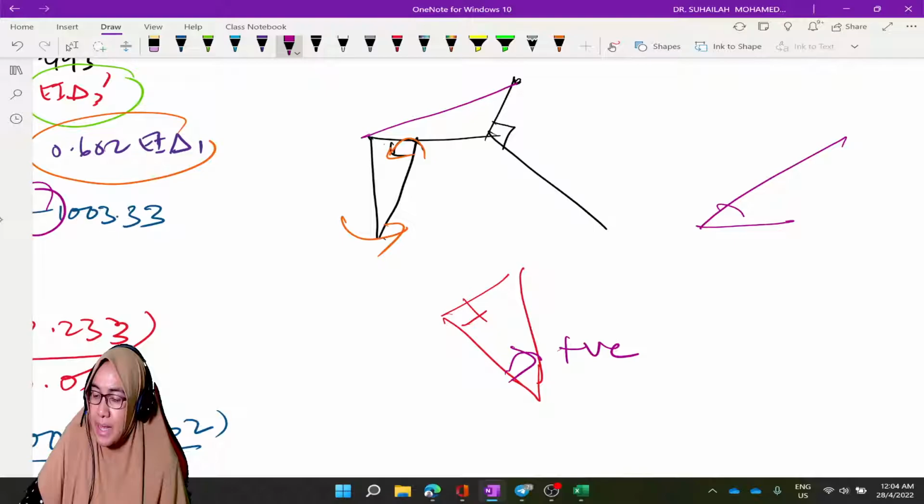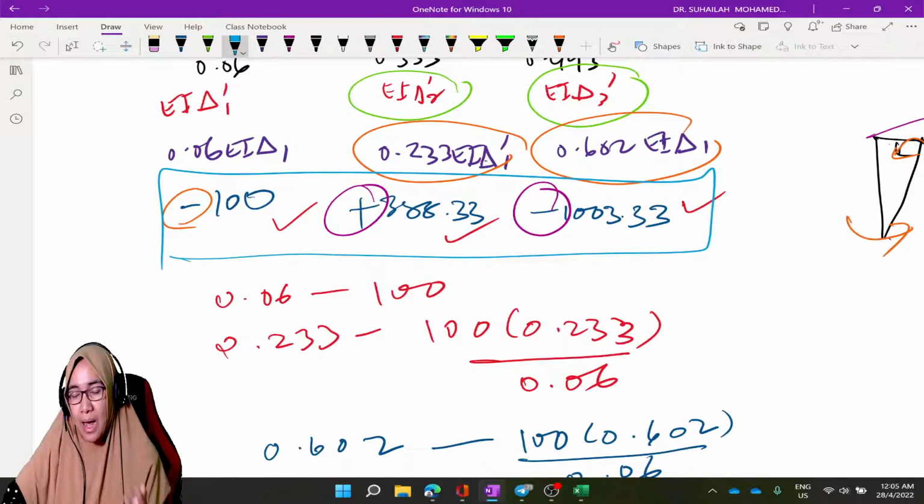The most difficult part in frame analysis is how to calculate FEM due to sidesway, because it is based on assumption. Whenever we analyze another diagram called the D diagram, where it is subjected to R prime, due to R prime the frame will tend to sidesway without loading.